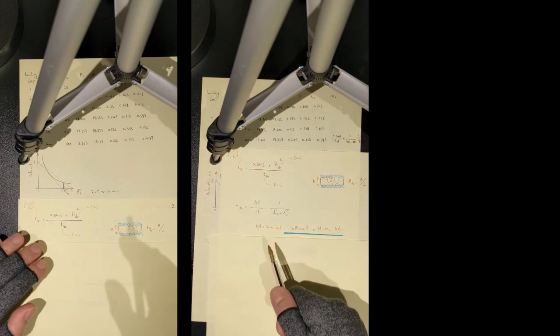But let me ask you a question. Well, you've taken a soil sample from a depth and you've done a oedometer test. Now for each loading step, you've got an M sub V value. Which of these M sub V's are you going to use to determine the total consolidation settlement beneath the future foundations? You have taken your soil sample, you have done a number of loading steps. For each loading step, you have measured a value of M sub V, coefficient of volume compressibility. Which of these M sub V's do you need to use in your settlement analysis?